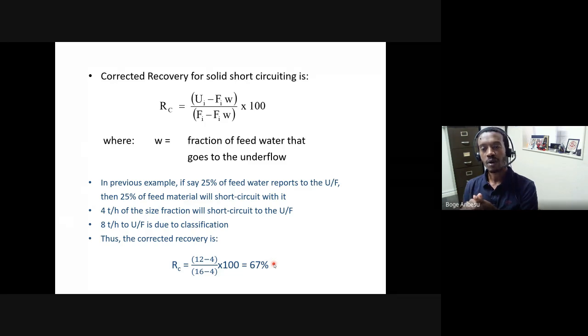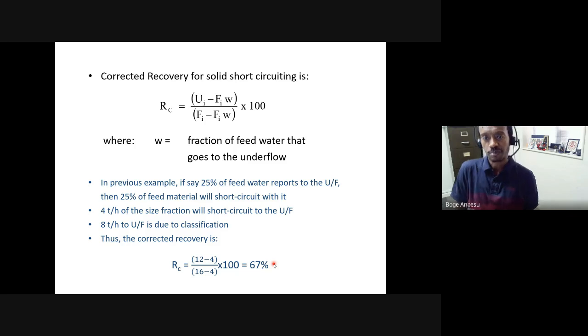Okay. That's why I said earlier, if you have too much water coming in the underflow, if it's spraying too much, as a spray discharge, then it's saying the underflow density is very low. It's saying there's a lot of water exiting. With water, you have not only coarse particles, but fine particles exiting as well. And therefore, the efficiency should be significantly reduced. Okay, so that's what this one is implying.